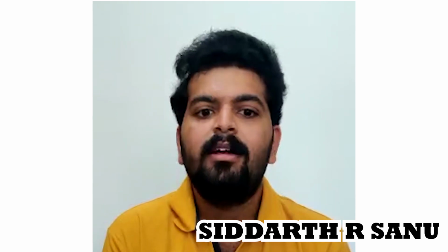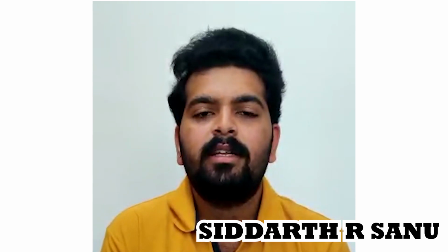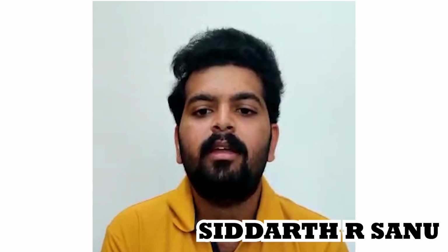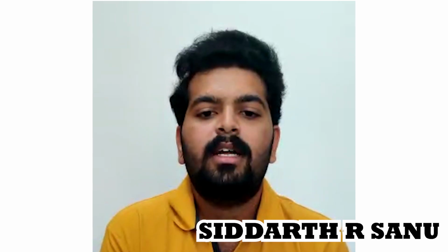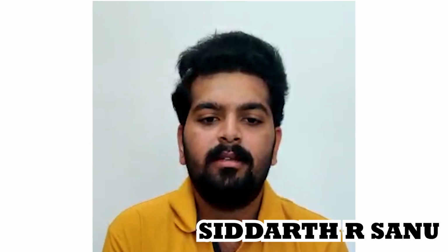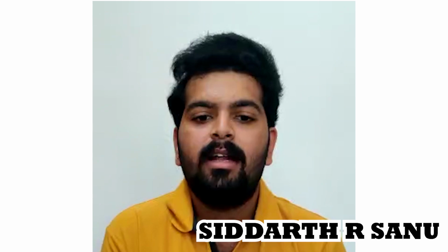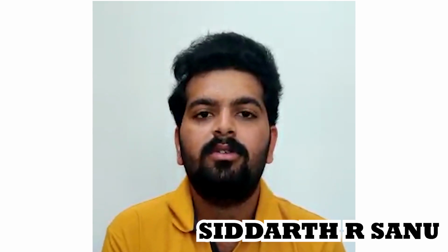Good afternoon. Myself Siddharth. Our topic is the Motor Generator Unit Kinetic. It is a component of the hybrid electric power unit. The unit is both an electric generator and motor, connected directly to the crankshaft of the internal combustion engine by gears. It performs two functions. Under acceleration, it helps the power engine, and under braking, it uses the energy that would have been dissipated as heat to recharge the batteries. It goes through that cycle several times, each lap drawing electricity to help the engine deliver power and generating electricity while helping the car to slow down.